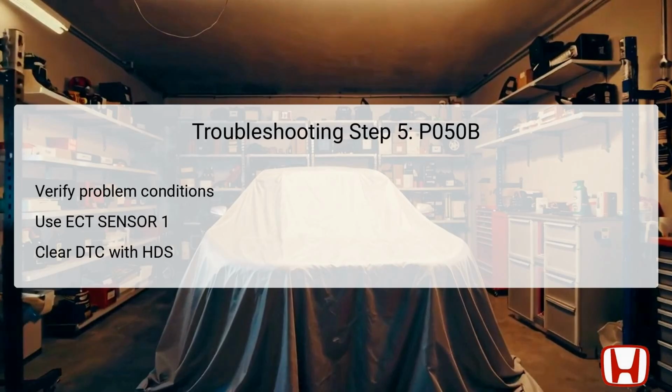After confirming the appropriate temperature, clear the Diagnostic Trouble Code using the Honda Diagnostic System, HDS. Verify that the issue still persists by turning the vehicle off and then restarting the engine. Allow it to idle for a minimum of 10 seconds before checking the OBD status for DTC